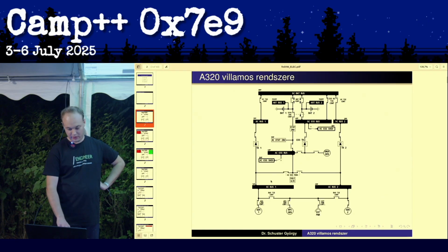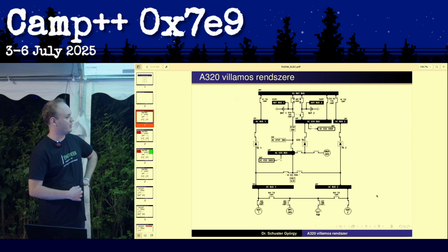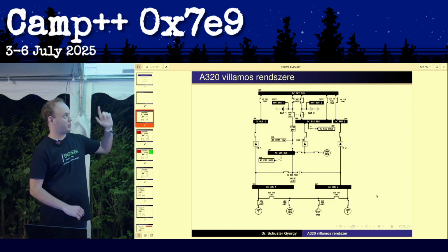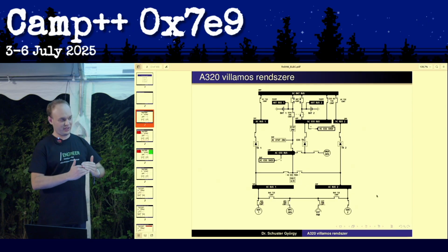There are two AC power buses for redundancy, and in a normal configuration they are supplied independently from engine number one and number two. There's a crossfeed between these inputs, but there's one important thing to know: the generators from engine number one and number two can power the two AC buses independently at the same time, but they cannot be interconnected because there's no way to synchronize them.